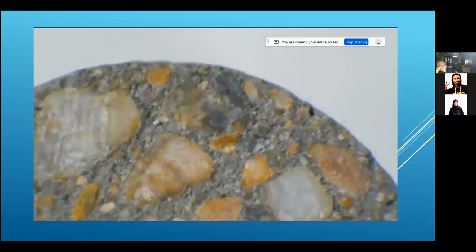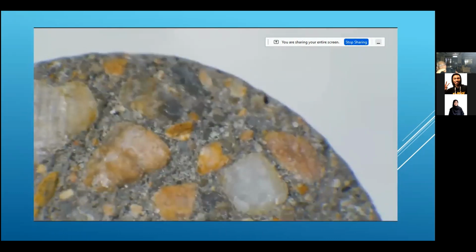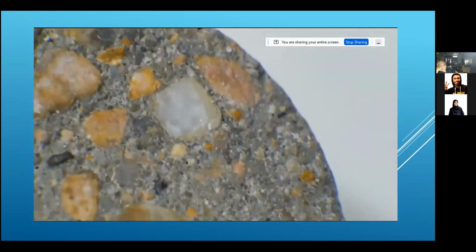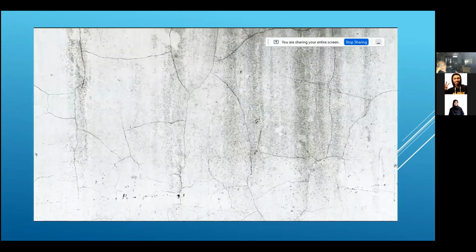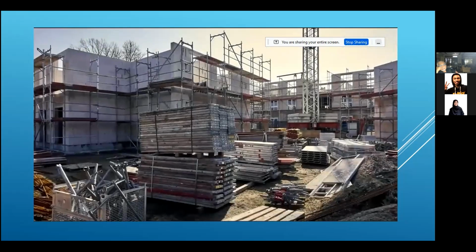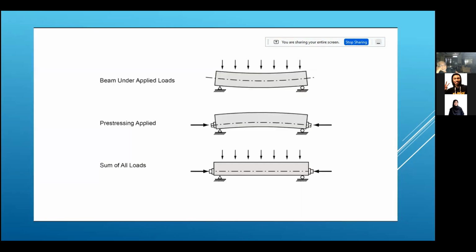After all, we're only asking the concrete to resist compressive forces, which it can do just fine with cracks. But there are some cases where you want to avoid cracks or the excessive deflection that can come from passive rebar. For those cases, you might consider going to an active reinforcement, also known as pre-stressed concrete. Pre-stressing means applying a stress to the reinforcement before the concrete is placed into service.